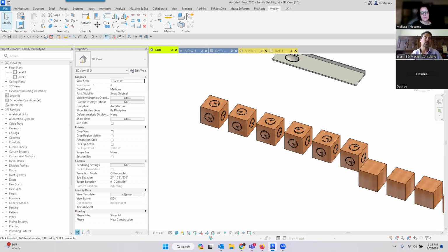I know with the new exporter, export to PDF out of Revit, you can move the files up and down and get them organized, but you have to go through and move the files up and down. I just want to do basically what I had for my schedule. The drawing index already has it. That's just what I want to do. Let me use the drawing index. And that's what PyRevit actually gave us to do, and that's the one I use most often.